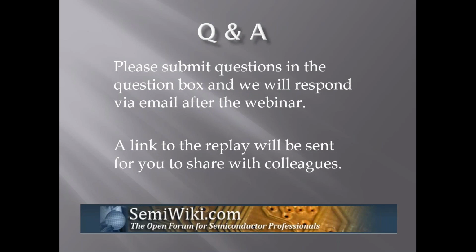First question. What type of plasma source is the microplasma ionizer? Thanks, Dan. The plasma ionizer is an ICP, inductively coupled plasma source, using a 430 megahertz RF power supply. It is an electrodeless discharge design, which offers stability and lifetime advantages. The plasma is energized using computer-controlled high-power RF pulses.